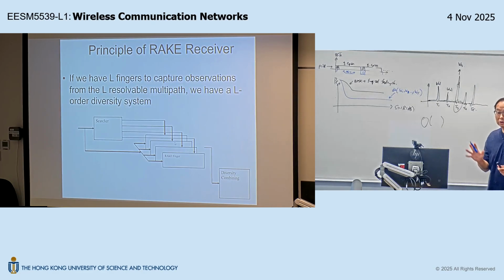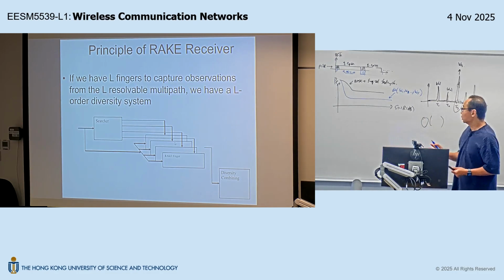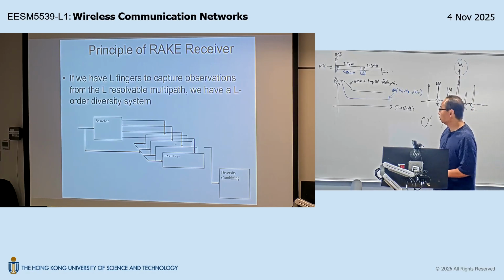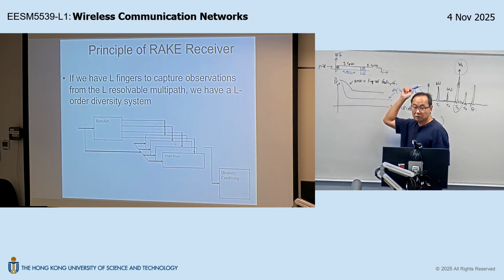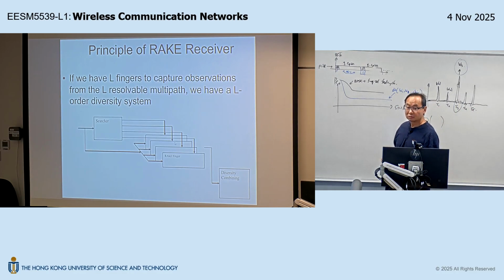But let's say this is too complicated. In the hardware design, I only have 1 physical despreader. As I said, the searcher in this case would assign the strongest path to despread. So if this is the case, what would be my error probability curve with this only despreader? Will I have this slope or will I have this slope if I only have one despreader?